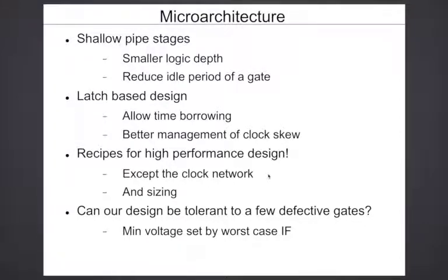Now the other thing also, what you can do for these very low power chips is look at the microarchitecture of the chip. How many pipe stages are there? I mean, you have a piece of function you want to compute. How many copies of the function do you have so that you do things in parallel, and for each copy, how many pipe stages do you break it up into? So these are essentially microarchitectural questions. As a designer, even if you're writing RTL, you have to decide how to break up your function, right?